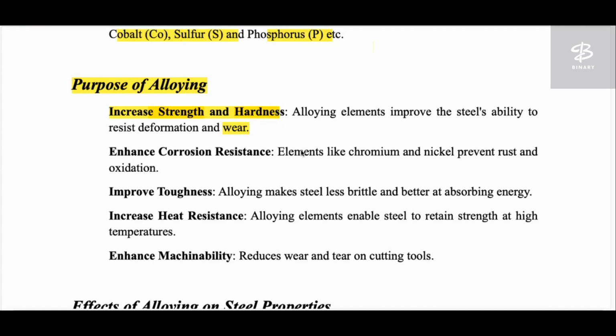Okay, so if you would like to pinch, or insert some kind of needle type material into a harder material, then it will not allow it to be inserted inside the material. That is known as hardness. If they are less hard, then that material will be pinched inside very easily. Or the very simple thing is, if you would like to scratch the surface of the material, if it gets scratched, it means it is less hard. And if you are not able to scratch anything, it means it is higher hardness. And if it is easily scratched, then it means it is very less hard.